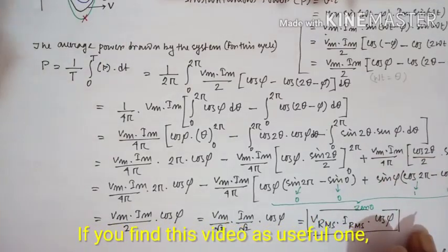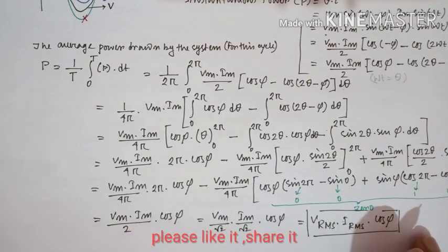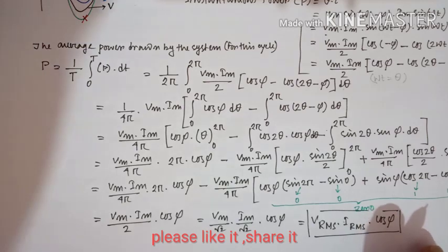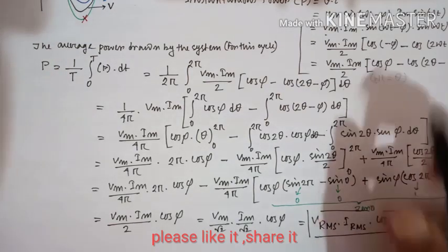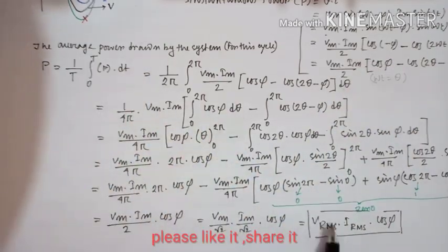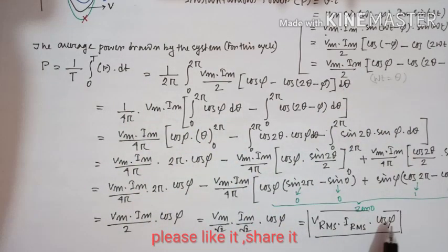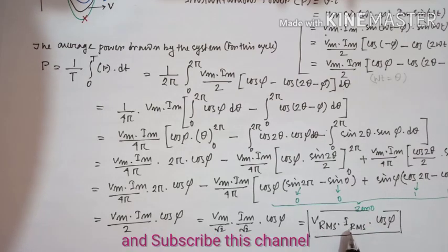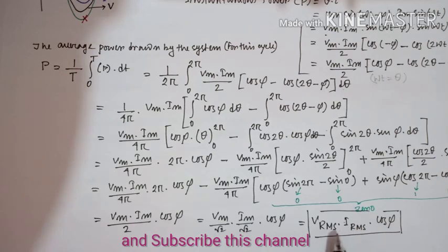So basically what we have done, that wherever it is an AC system or DC system, power is basically V into I. If we put their equations and after doing all this calculation, I will get V into I into cos phi. We need to remember the V and I that we are talking about here are basically their RMS values, and by using all the ammeters and voltmeters, whatever current and voltage you measure are basically their RMS values.